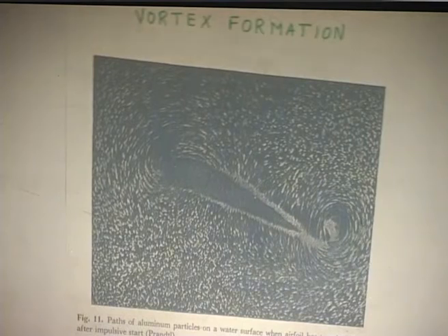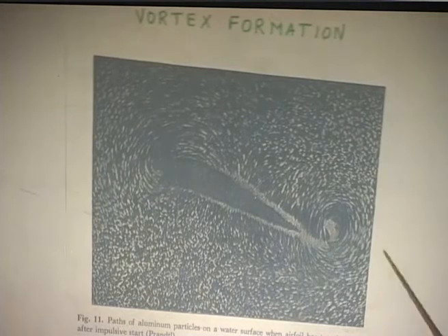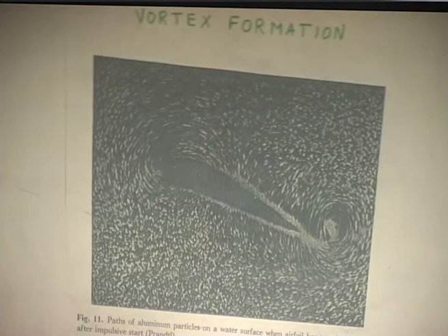You understand, because initially there is nothing, so it is shed. When you shed it, what will happen? Because of the oncoming velocity in aerodynamics, this gets taken back, and the effect of that vortex on the aerofoil is, you say, 0. So, I have only a bound circulation.